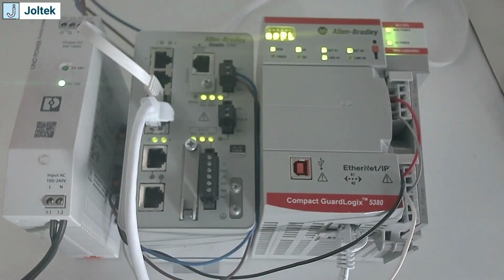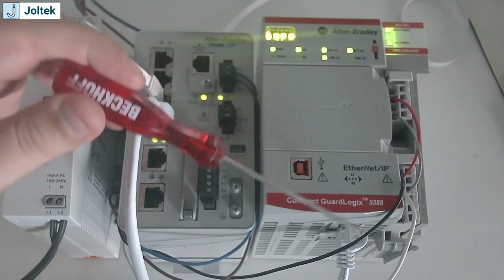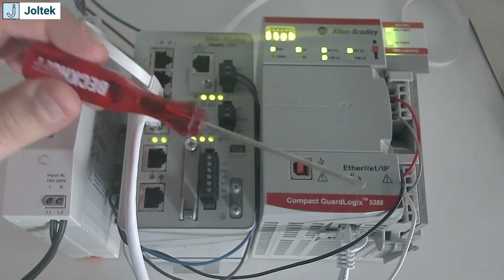So in this case, remember that we have the switch on 192.168.1.70, and the PLC is going to have two interfaces, one of which is going to be 192.168.1.5, and the other one is going to be the plant side. We'll talk about the theory in a separate video, but what you need to know is that we are on the same subnet between the PLC and the switch on that specific port of the device.